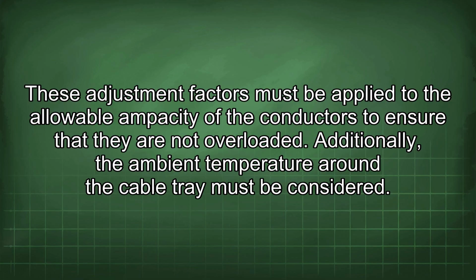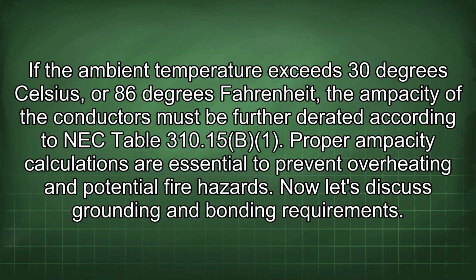Additionally, the ambient temperature around the cable tray must be considered. If the ambient temperature exceeds 30 degrees Celsius, or 86 degrees Fahrenheit, the ampacity of the conductors must be further derated according to NEC Table 310.15(B)(1). Proper ampacity calculations are essential to prevent overheating and potential fire hazards.